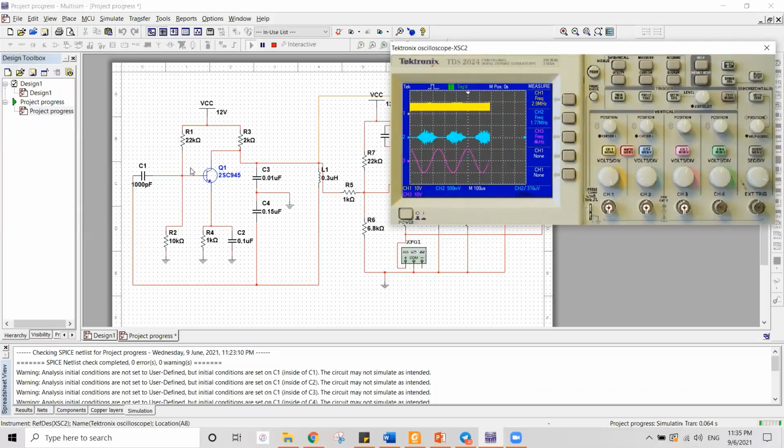The untuned oscillator is the Wien bridge, and the tuned oscillator is divided into two: first the Colpitts oscillator, then the Hartley oscillator. For this design, we use the Colpitts oscillator. As we can see, we use many more capacitors than inductors.